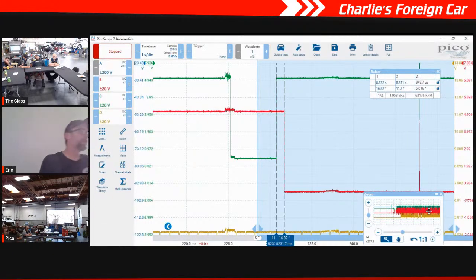Yeah, no, I just mind melded myself for a second there. When we advance the cam, we move it so that we're opening the valve before 0 arrives, right? So 0 would come closer. That would actually be retarding it. I'm backwards on that.